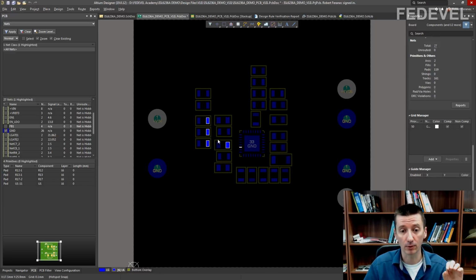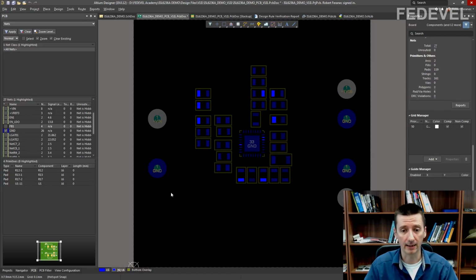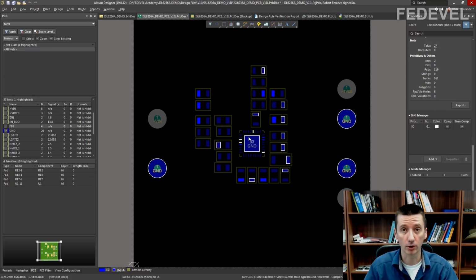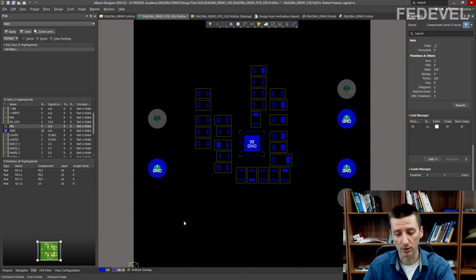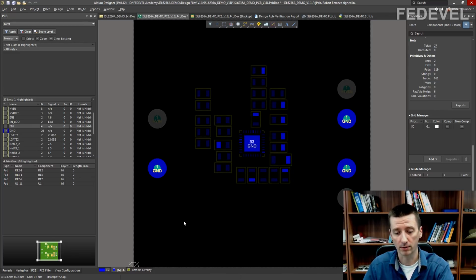So even if you are doing layout, you still see what pins you need to connect. I know we have this second feature, when you just hover the cursor and you can see where everything is connected, but this is only at the moment when you are holding the cursor there. You cannot really use this during layout. During layout, you would like to use Ctrl, left click, and this way you can keep seeing what pins are connected together. So hover the cursor, Ctrl, left click, and use square brackets to change the intensity of the colors.